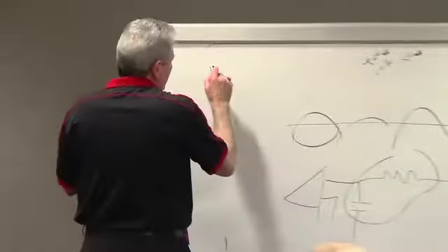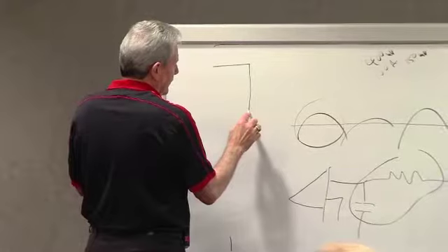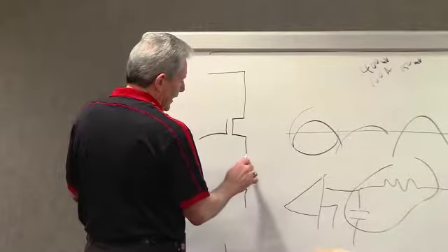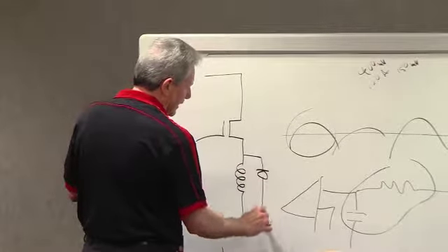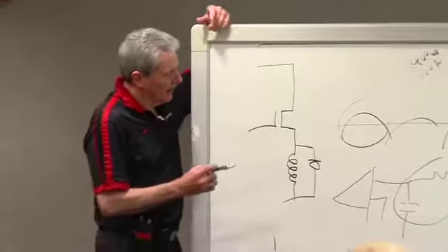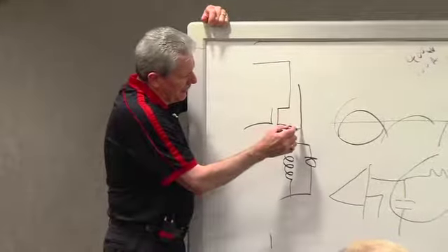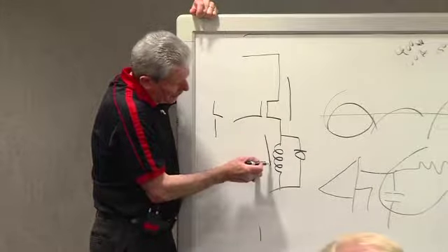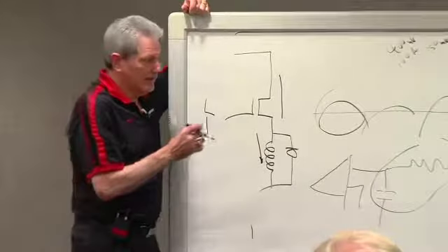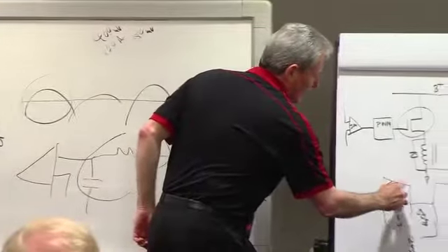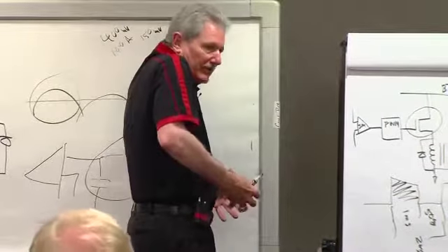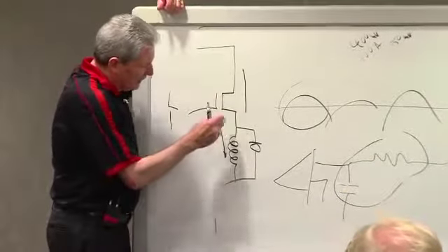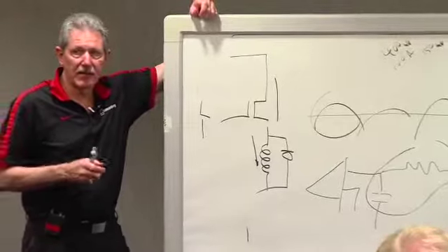Let's go back here a minute. Now I put the switch in the high side. Here's the field. Now I'm going to explain why you have a diode trio. So I push current, this is a switch. When I close the switch, current begins to flow in here during this time. So I'm filling up that field with magnetic energy. Now, at 50% in this case, it turns off. So now the current has stopped.